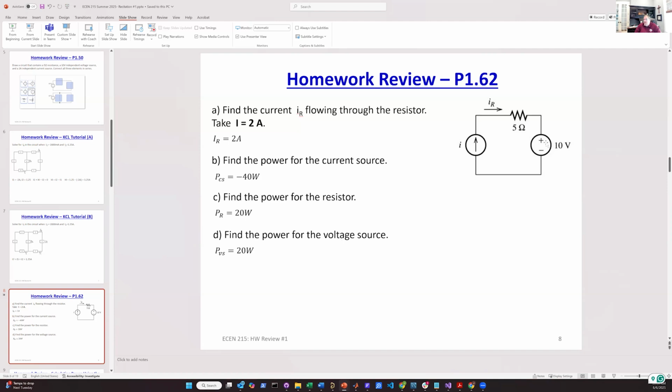Well, here, even though this is a power supply, and usually power supplies we expect to generate current and push current out its positive terminal, this one is actually absorbing, because this is an ideal current source. The current source is going to push current into this power supply just by the nature of how these are ideal devices. And as such, we have 2 amps going in the positive terminal. The power equation, P is equal to V times I, is 10 times 2, and we end up with 20 watts.